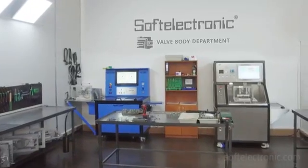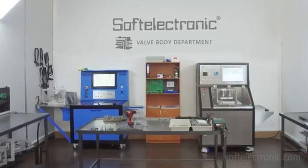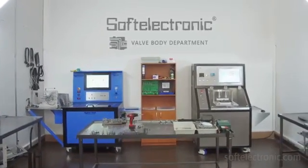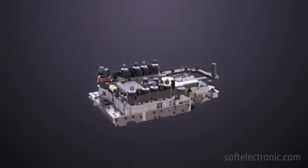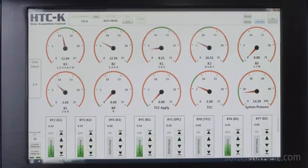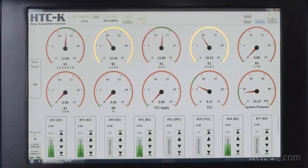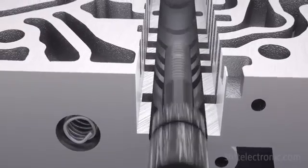Soft Electronic is the only company in the Balkans and one of the few in the world which owns 2 of the best stands for mechatronic testing. If the tests pass successfully, the valve body is assembled to the control unit and the mechatronic is mounted in the gearbox. If the tests show deviation from the working parameters of the valves, this could be due to wear of the valve or the valve seat.